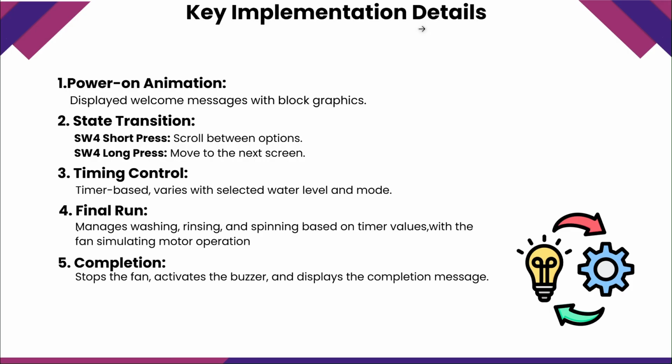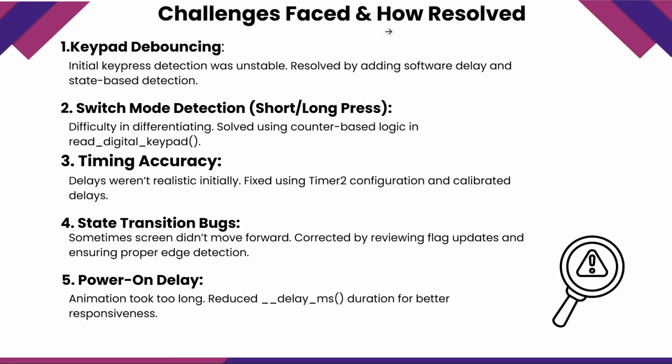Now, let's discuss the challenges faced during this development and how I resolved them. The challenges that I faced were: first, keypad debouncing. Initial key press detection was unstable. This was resolved by adding software delay and state-based detection.